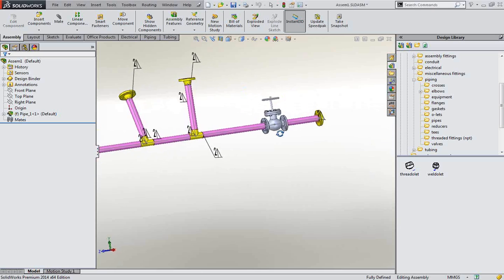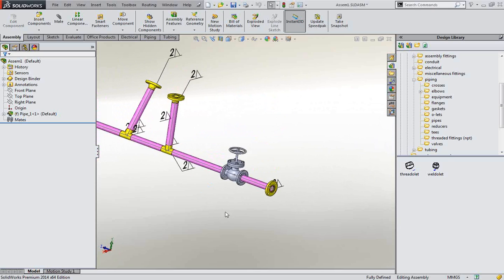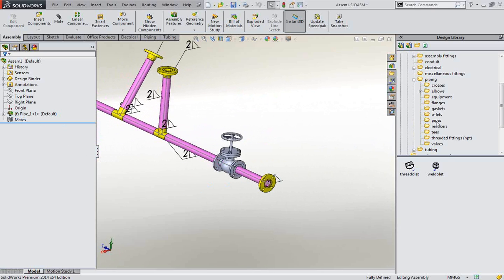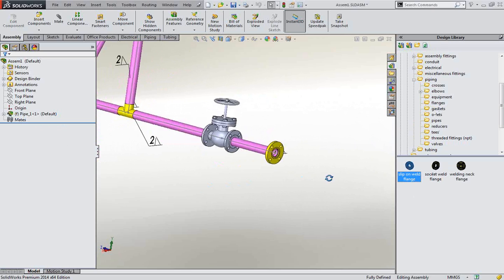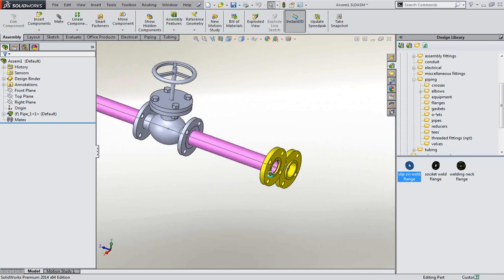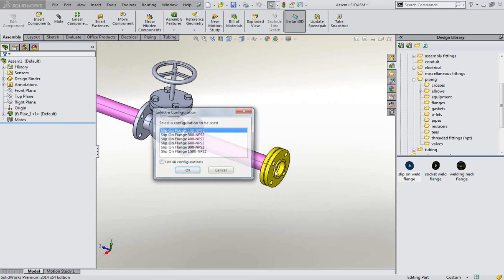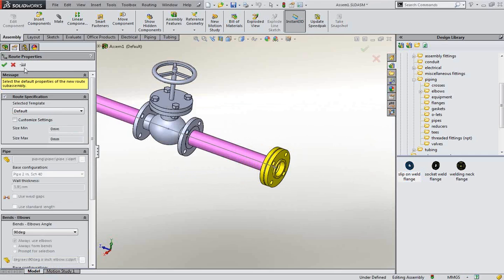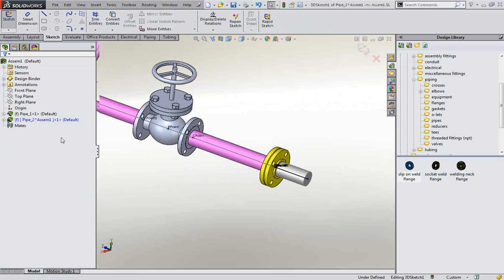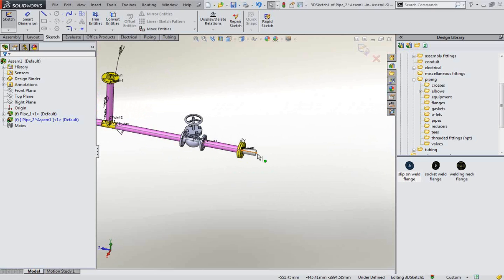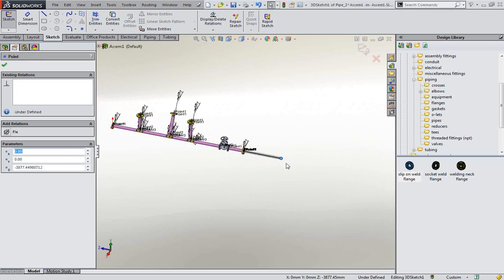Then we can further add in a pipe segment. Okay. Adding in more flanges. So clicking to it. When you click OK, again, it will start off as another new pipe segment, and you can start creating your piping design.